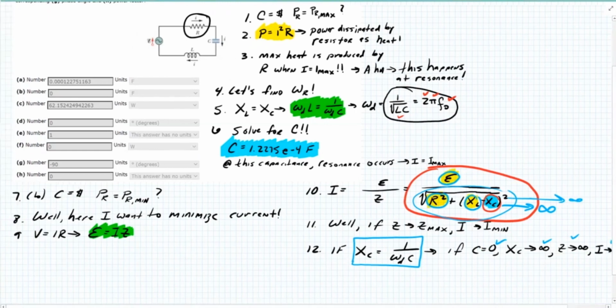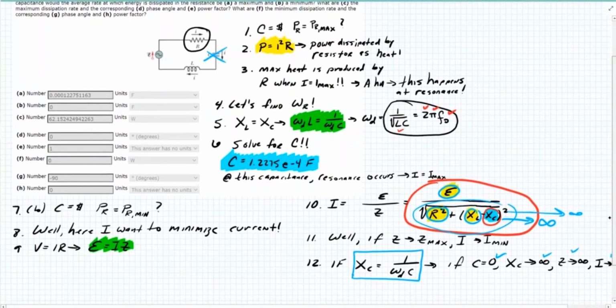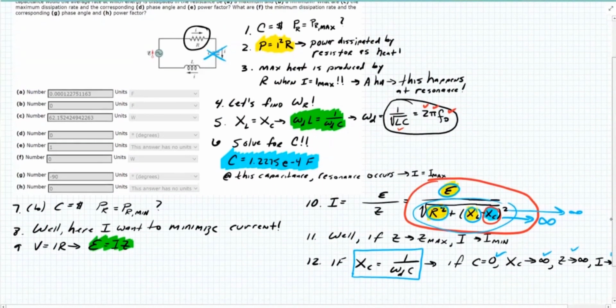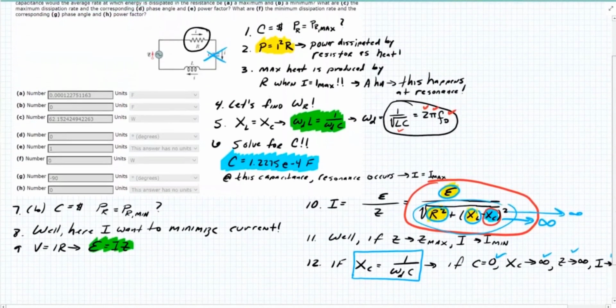And what does zero capacitance mean? It means you take the capacitor out of the circuit, in essence. Or sorry, I should say it's a blank circuit. It's an opening, it's a gap. So it's an open circuit. So if you just surgically remove the capacitor from the circuit, there's basically no current flow. This is maybe one way to look at it.